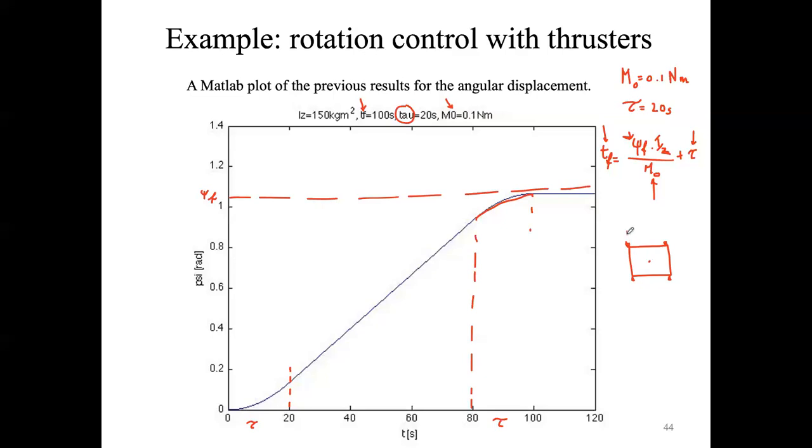If these thrusters are not perfectly aligned, you are not only going to have a torque that gives you the possibility to reach a specific altitude, but if there is a misalignment, you're also going to have, for example, an undecided thrust, an undecided delta V. This is another main disadvantage. And it usually occurs that the spacecraft thrusters, because of vibration or thermal deformation, tend to have small misalignments that lead to delta V during maneuvers.